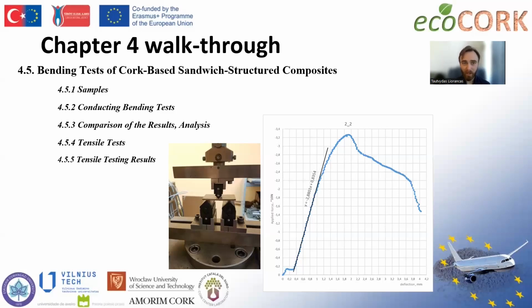reinforcement plates. Comparison of the results and analysis showed us that in the bending tests, the cork filler gives a very big difference when we compare it to the foam filler. Therefore, we conclude that the filler in the bending scenario is very important. We also discussed and concluded that the different grain sizes in the filler cork material are also impactful for the bending strength of the sandwich plate panel.